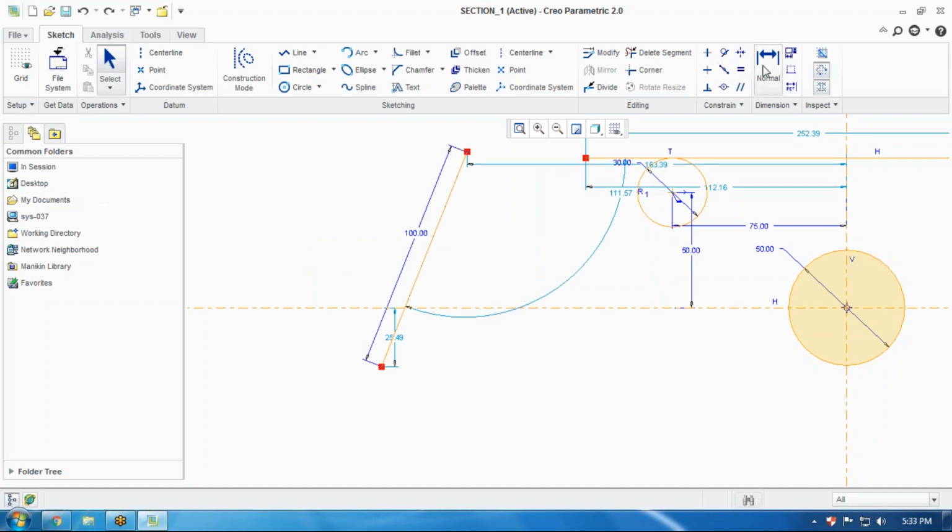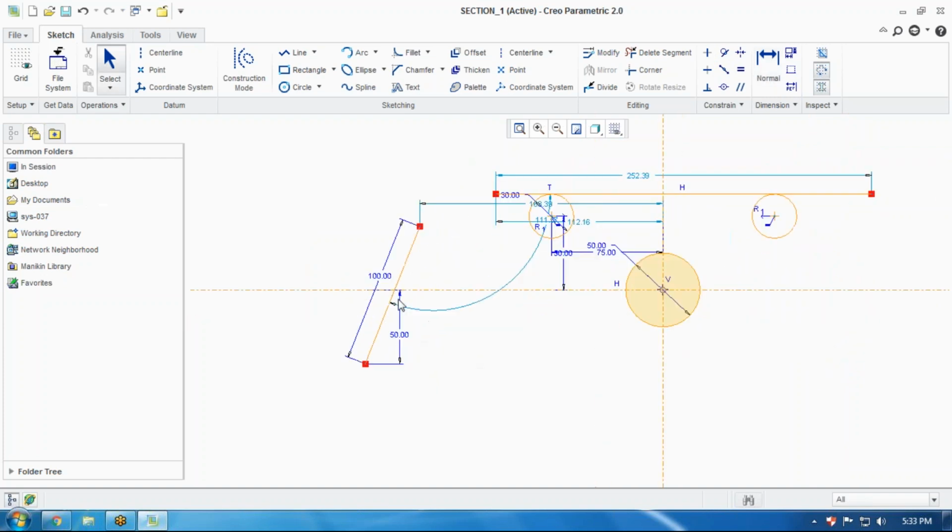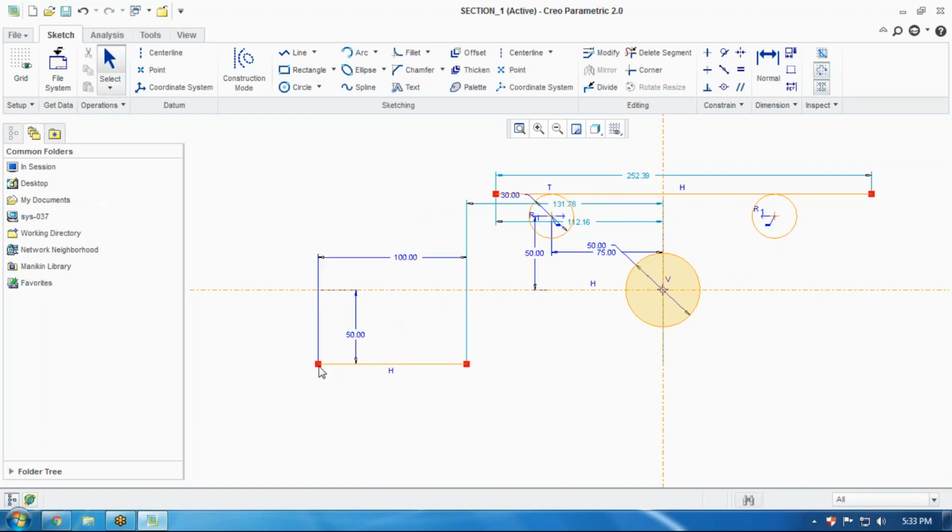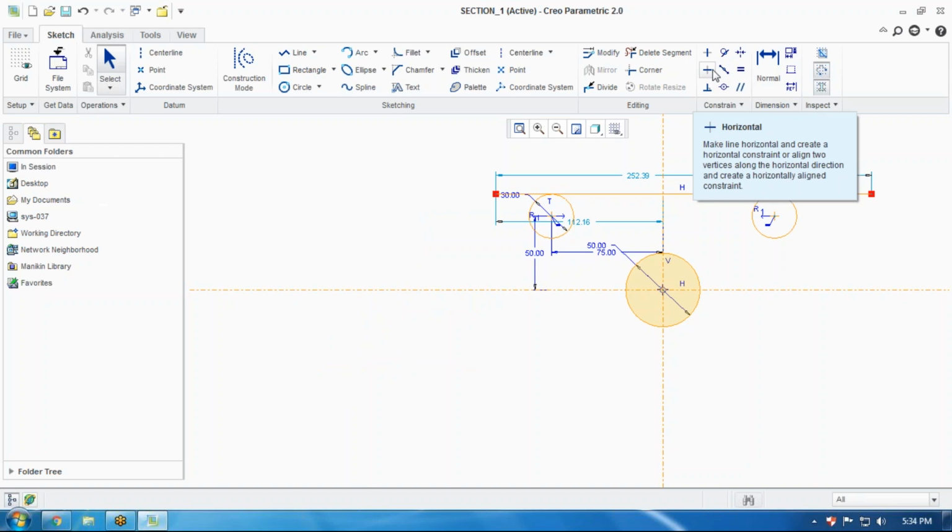Now what I'm doing here, I'm again giving the same dimension command here and putting the dimension in relationship with this point. So we'll see that we are giving the value here which is 50, and now I want to make it horizontal, so just go for horizontal, and you will see the center point will not differ, the size is the same, only one point was unstable. So now the line is totally, completely stable, right? So this is the utility of the constraint bar, right? This is vertical, horizontal, tangential, symmetric, this is equal. Now we are working on midpoint.